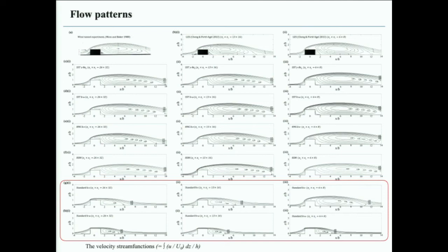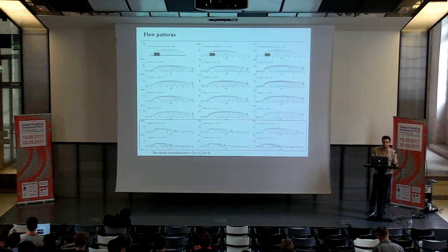It means that if you consider the recirculation center at the wind tunnel, the black buildings, there's a recirculation center. You'll see that these two bottom turbulence models, standard K epsilon and standard K omega models, cannot really properly reproduce the recirculation center. And that means that they not only give us the wrong answers, sometimes they can completely mislead us in design decisions. So this is very, very important for us.